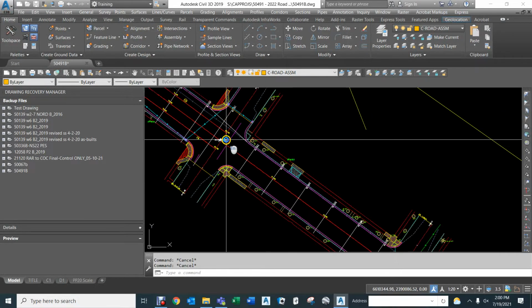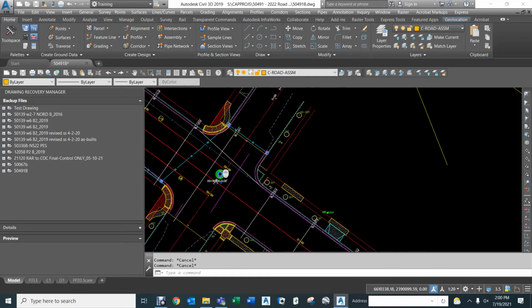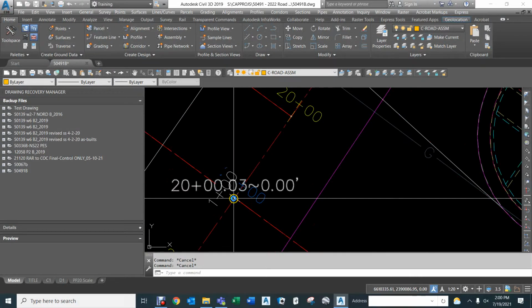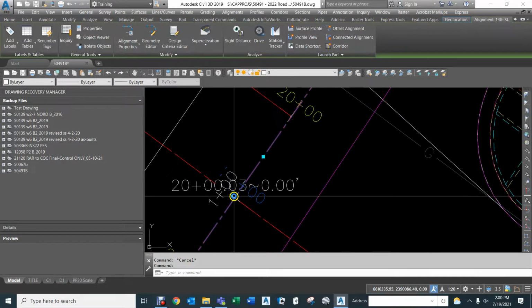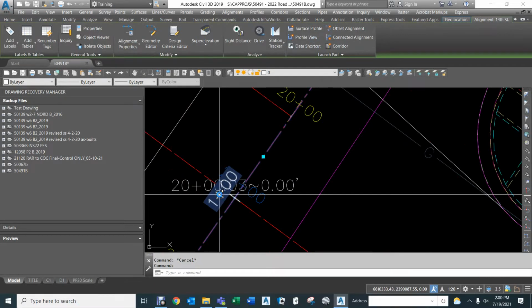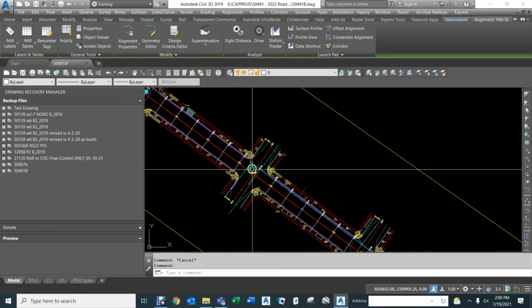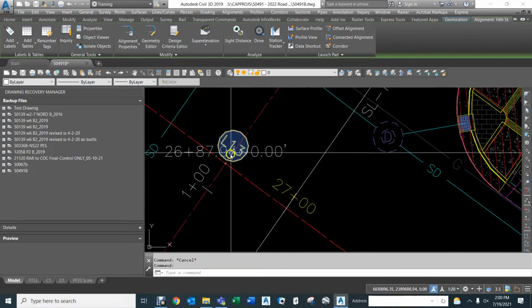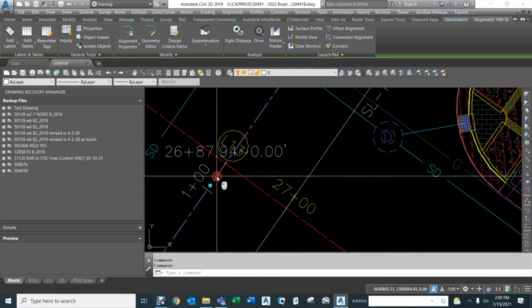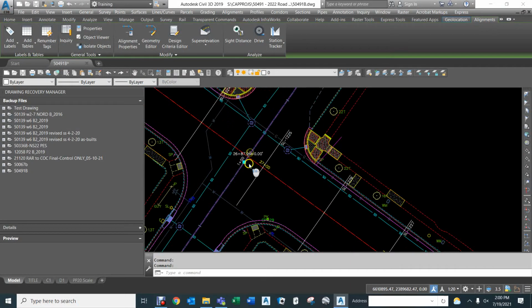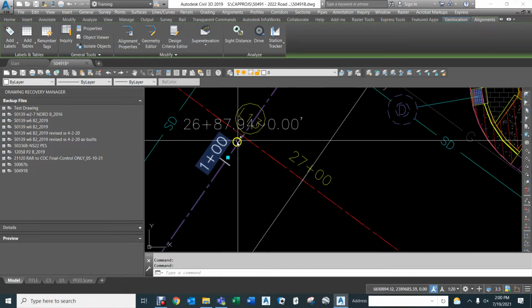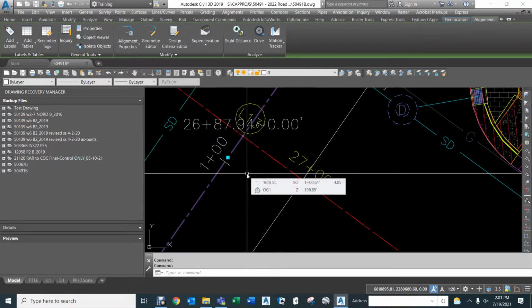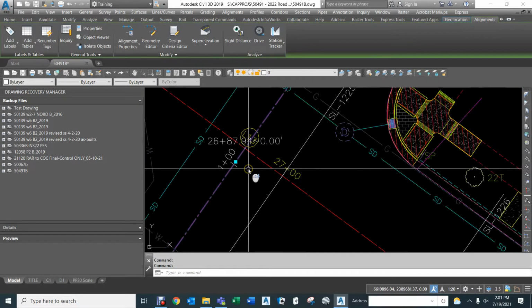And we've already done one. We've done this one right here, which I think is 14th Street. And we've made the center line of this minor alignment equal to 1 and a pair evenly, so 100. We want to do that to the rest of the streets. This one's done. This one is not done, so we'll run through this example. What we want to do is click that alignment, and you can see 1 and a pair is right here, and we want it to be right there at the alignment. It's going to help us lay out the roadway down the road, in the near future.